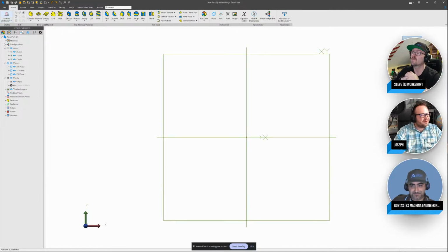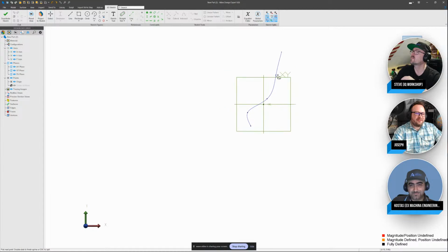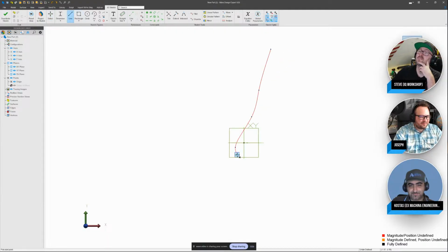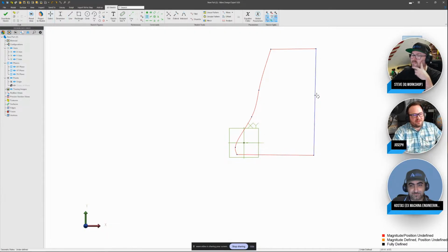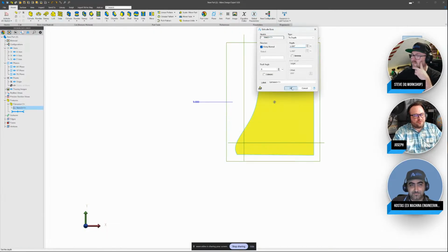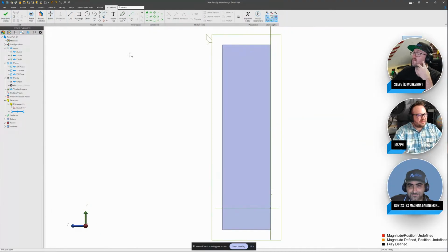So if I create a new part, and maybe on my XY plane, if I ignore orientation, I'll create a spline here. I kind of like how splines are not constant radius and not linear. And so it kind of represents perhaps some of the most difficult paths that we can go on. And I'm not really constraining my sketches. So in a serious project, of course, we would constrain our stuff. But here, I'll make a kind of difficult path in 3D space,